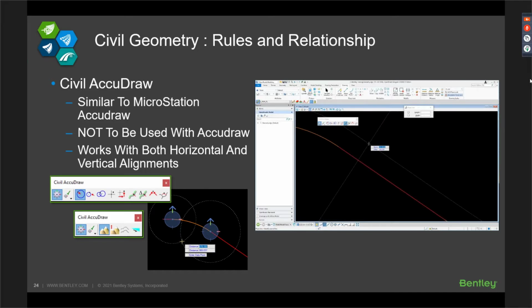So like what you can see here, it can be in the context of your horizontal geometry, like probably laying them out based on station or chainage or maybe XYZ or XY, or coordinates, be it polar or Cartesian coordinates. And then once you shift to vertical alignment, it allows you to invoke Z or elevation relationship, maybe a delta or change in elevation from one profile to another, and so on.